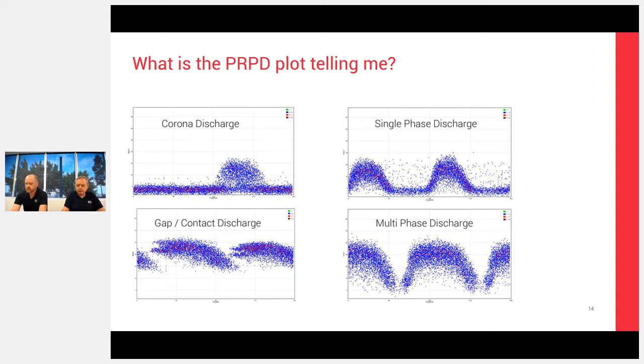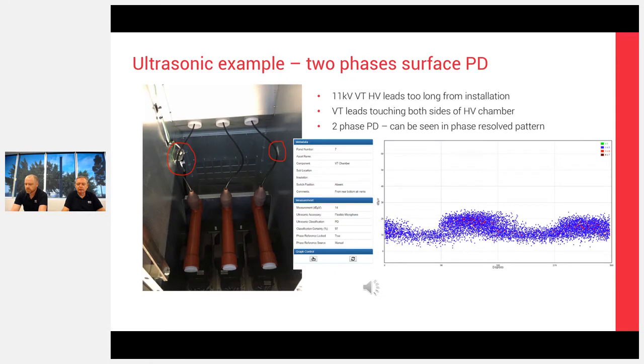Okay, so the next slide will show you an example of how we use that to interpret. So we've opened up, we've had the phase plot, as you can see here. It's quite a large clustering, so it's happening for quite a long period of time. So that gives us an indication that, again, there's more than maybe one phase involved. Sounds like PD. It's that crackling sound again. The algorithm in that particular case indicated 97% certainty of PD, and when we opened it up, lo and behold,